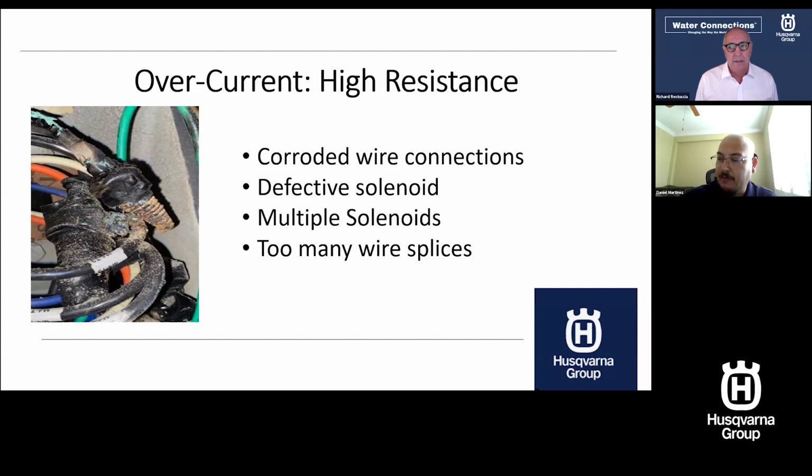I'll share a little story. We have what we call an enterprise account, a large private entity, and they had issues. The controllers were having failures, components failing. So they came to us and said, hey, our ET water controllers are having problems. What's going on? We're having computer boards get fried. There's a problem with your controller. And luckily, with our controllers, we log all the data, and we came to find out, hey, look, your controller's been reporting these overcurrents for over 6 months.